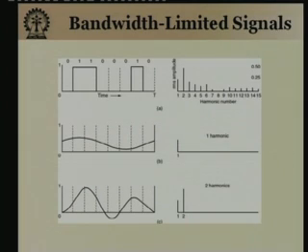So, the channel, if it has to carry the digital signal, has to be able to carry all these so called harmonics. Harmonics means this sin x function, this sin 2x function, sin 3x, etc. All these harmonics it should be able to carry. Whereas in the second figure, B, it is a pure sine wave, so it has just one harmonic, something like a sin x.